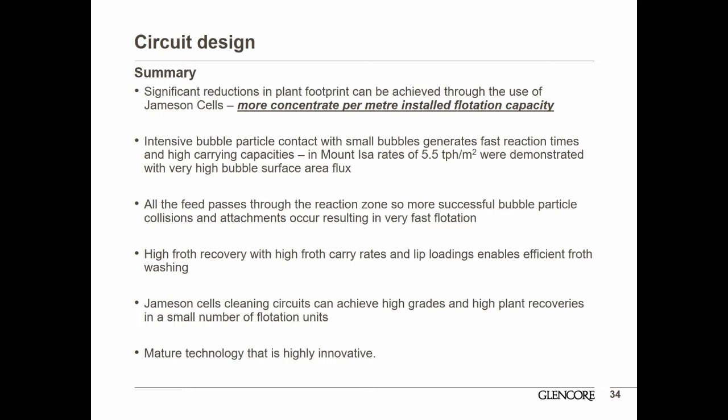Unlike other flotation technologies, all of the feed passes through the reaction zone with no bypass. This results in significantly faster flotation rates and higher unit recoveries. In particular, this gives exceptional recovery to difficult to recover particles such as gold and molybdenum, which often lag in other technologies. The stable froth results in high froth recoveries, high carrying capacities, and acceptable lip loadings. This enables effective froth washing, and it reduces the entrained gangue in the concentrate.